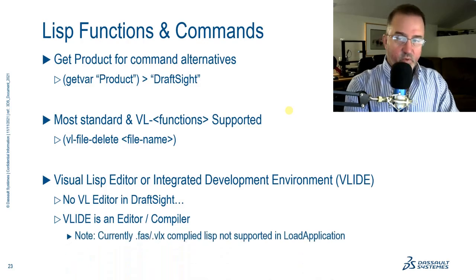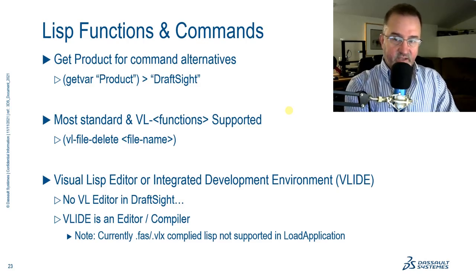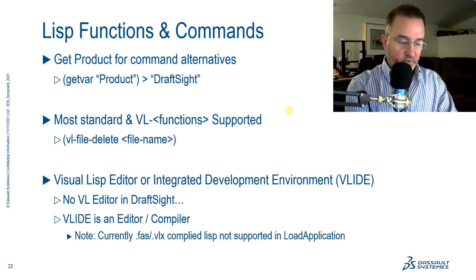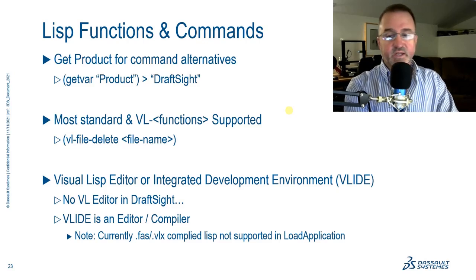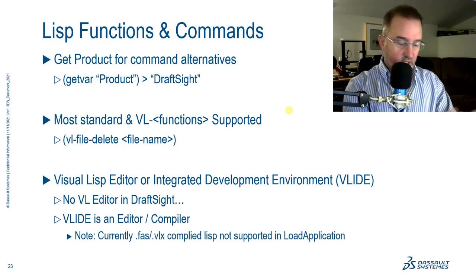Now, the other thing I wanted to point out is that currently with DraftSight, we do not support FAS or VLX compiled Lisp code. So if you go into load application, you can load up your Lisp files, your LSP files, but you cannot load up or run anything that's been compiled via that VLisp editor.